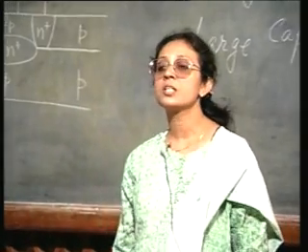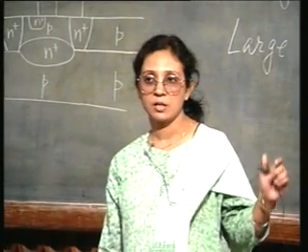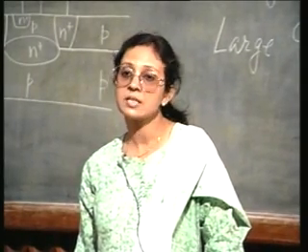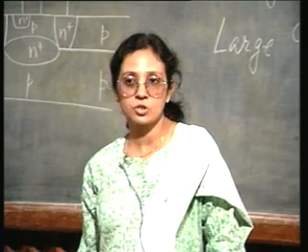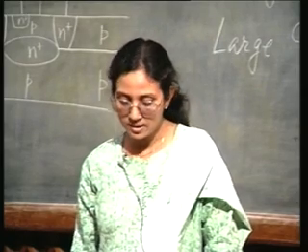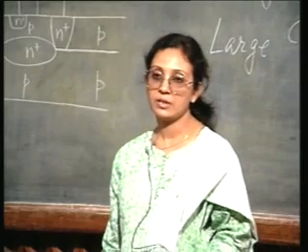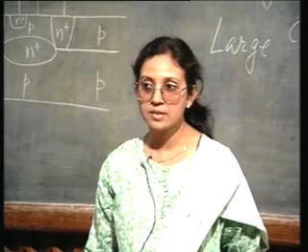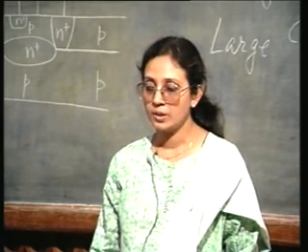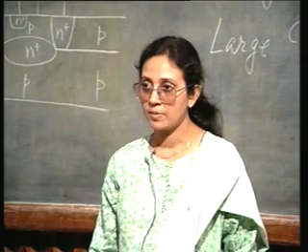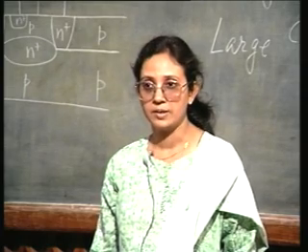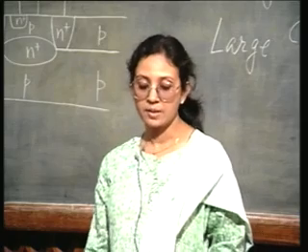Okay. And here of course, you have overcome the first problem which we had in the previous 3 diffusion techniques, that is, the problem of collector resistance is sorted out. Now, your collector is N plus, therefore, the collector resistance is very small, but even that can create a problem. Since collector resistance is very small, you may have punch through in the base. When the base collector is reverse biased, because the collector is very highly doped, entire base can get depleted. So, punch through in the base may occur.